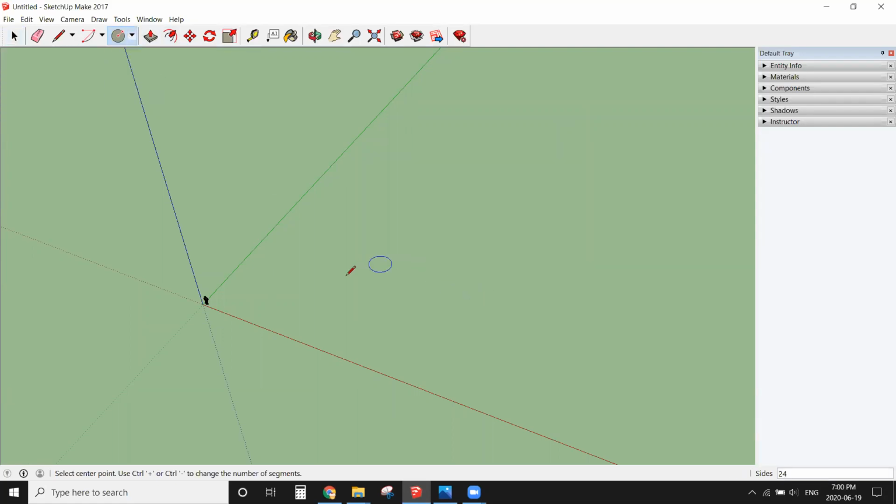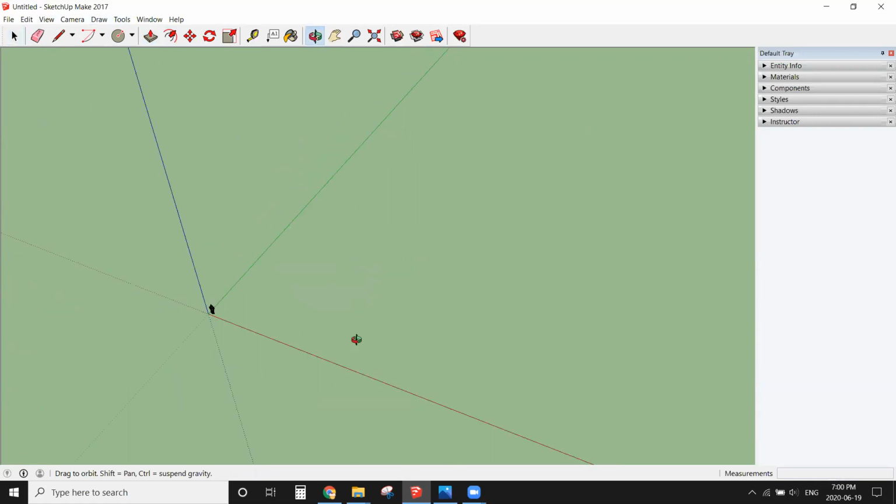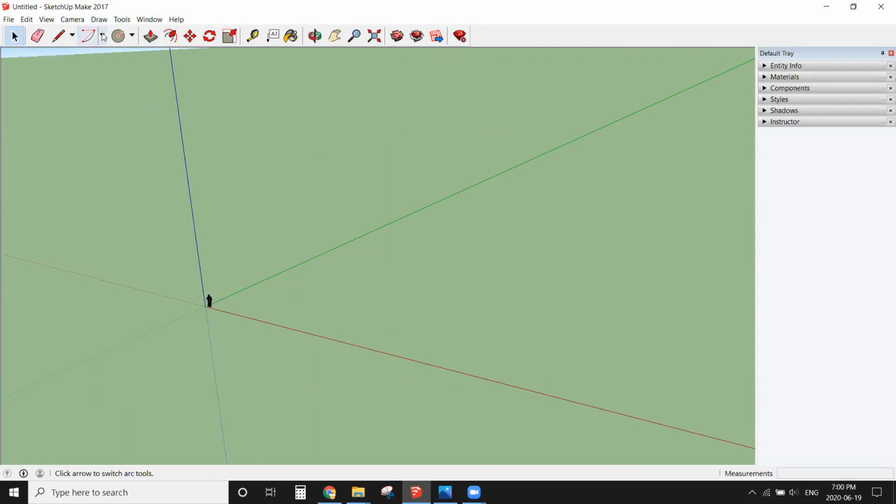Now let's try with a circle. So if you create a circle, you can click down and it will give you the dimension of the radius. So I want a 4-meter radius, enter, and it creates that exact size. Again, we have learned that we can pull and we can push these shapes to create whatever height we want in 3 dimensions.